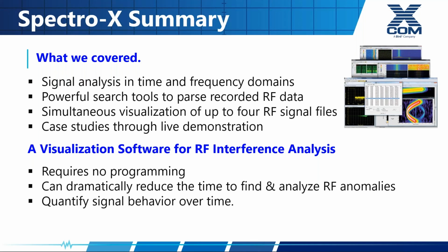And then we tied all of that together into one continuous recorded file. So in the file, you may have noticed there was some Wi-Fi, there was the Bluetooth hopper I pointed out, some linear frequency modulated sweeps or chirps, as well as some interferers that we injected. So you can take your exported data and actually create new waveforms for analysis or even regeneration and playback over RF.